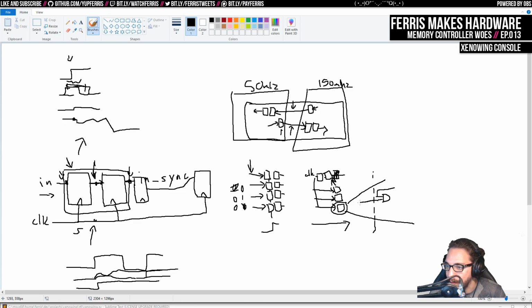And then this is the actual input. And then this is the input to the flip-flop. So you only accept that value when some synchronous signal says that that's okay. And if that synchronous signal is based on this synced signal, then these will have enough time to settle by the time you actually latch the data, once you've decoded the fact that there was a change on this synchronized signal.